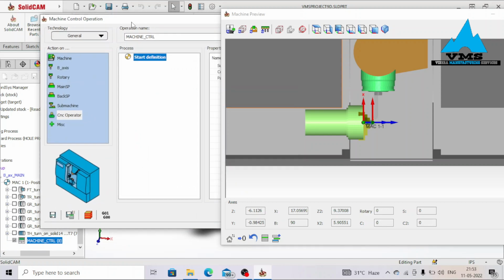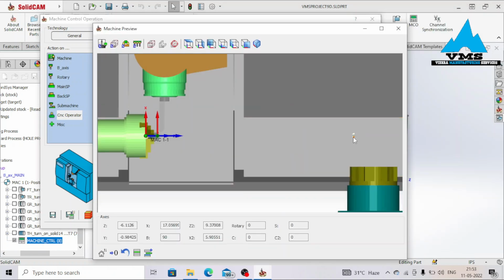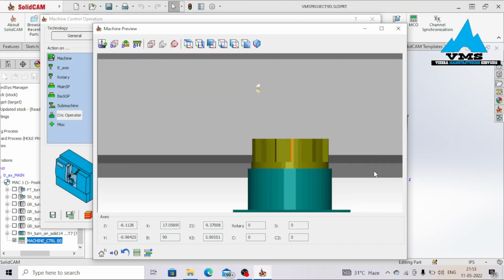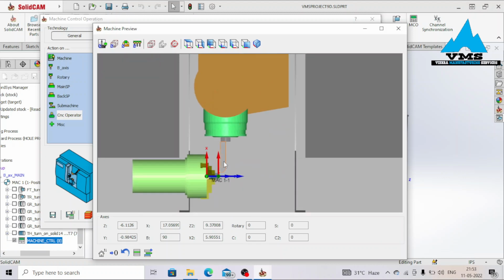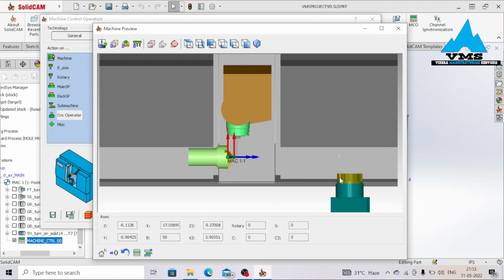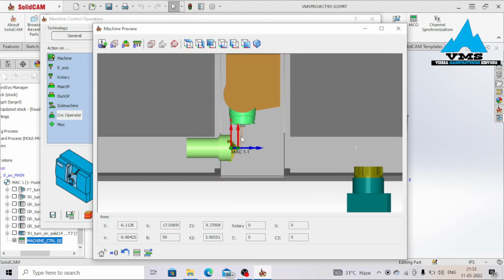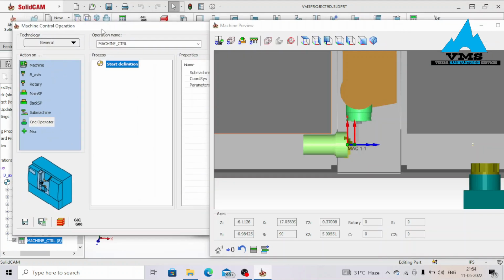So I'm going to show you guys how you can actually make the part transfer automatically. If the sub spindle has to move from this point to the main spindle, two things can happen. We could get a collision with the sub tool turret, as well as a collision with the tool. We want to make sure that the sub tool turret is out of the way, and equally this tool is out of the way to avoid any collision. These are the steps you have to perform.